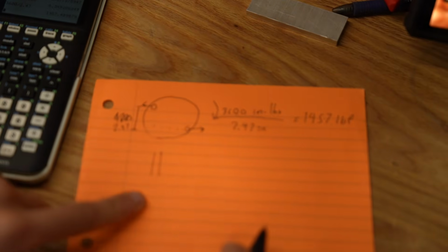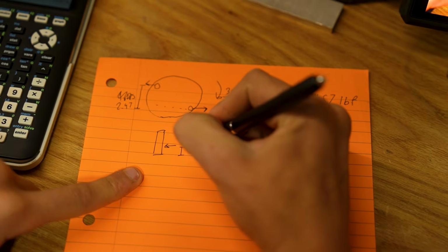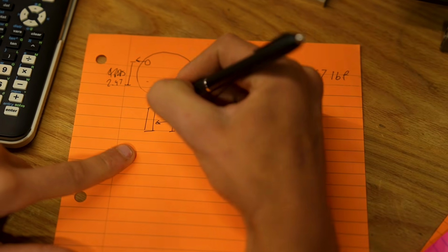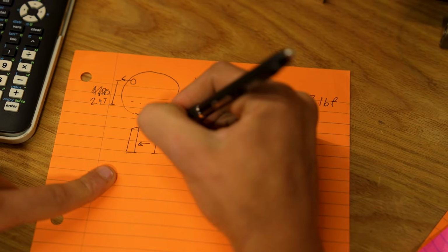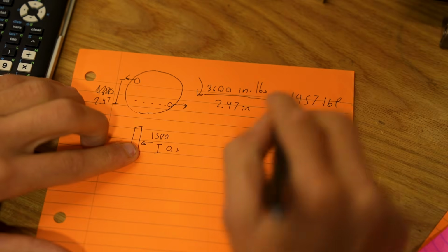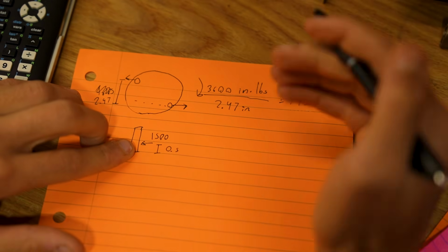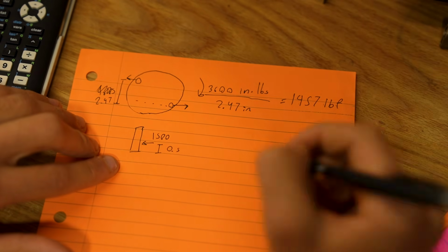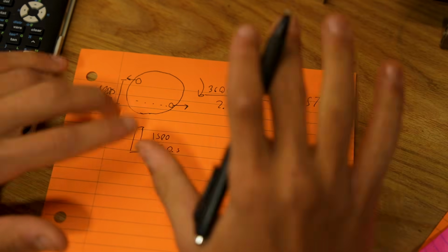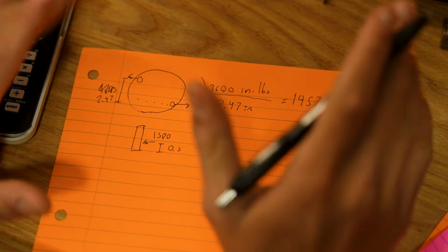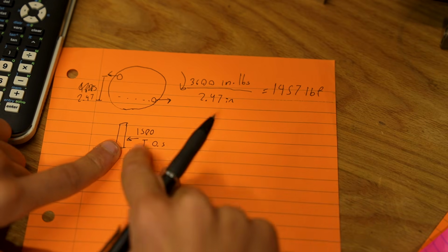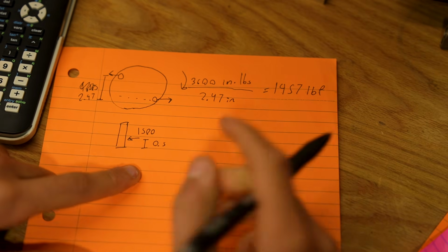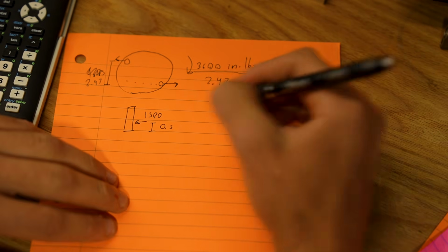So this is going to be a side view of our nub here, 0.5 inches up. We're going to round this to 1,500, which is, we keep saying conservative. Conservative just means that we're making it worse than it really is, right? A non-conservative assumption is one that's kind of idealizing your case to make it better than it is. But rounding up from 1,457 to 1,500 makes the math easier, and it increases our force.